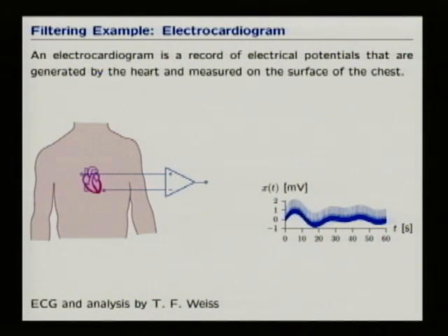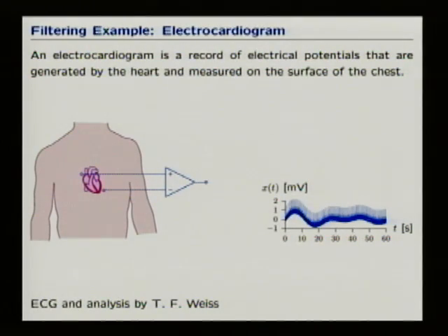And so I want to illustrate that by thinking about a hard problem in signal processing, and that is an electrocardiogram. So first off, it's completely amazing that you can measure an electrocardiogram at all. The voltages produced by cells are on the order of 100 millivolts. That's true for all cells for extremely fundamental reasons, which, if you're interested in, 6021 has a lot of information about why there are fundamental physical limits on what kinds of voltage a cell can make. So the voltages are small,